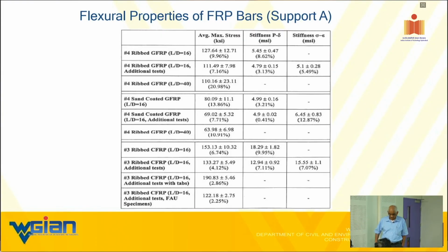In a bending response, it's linear up to 45% of the ultimate, but in a column it may be linear up to 70%, because eventually you will never have perfectly collinear force generation. Any slight amount of non-collinearity will bring you bending.